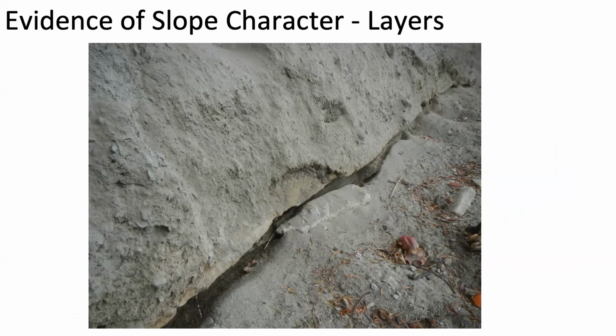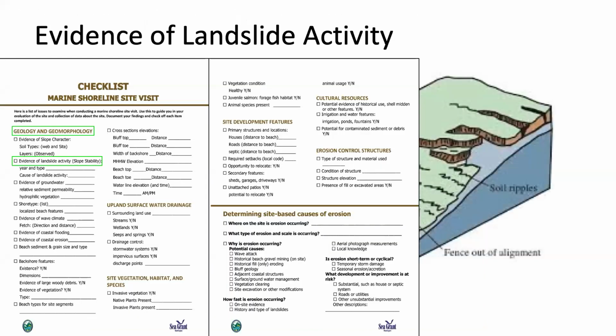So in the photo there, you can actually even see the accumulated fines piling up, and the little scarp that's forming over that impervious layer. So since we touched on failures, let's talk about slope failures. In the site assessment, the language is landslides and slope stability. Let's look at how slopes fail, how they can be unstable.